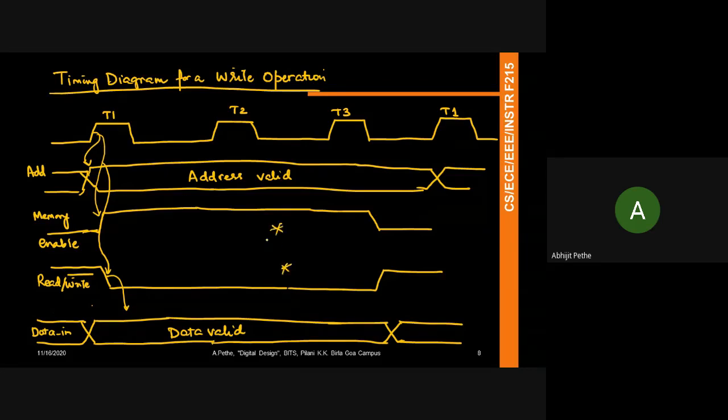So this is where timing signal generation becomes important. So we have special circuits to generate these signals. So these signals are going to be generated for specific times which you will need to design. So if I give you a clock like this, you should be able to design a state machine which can give you a memory enable signal like this, right? I mean, it's simple to do this kind of a design.